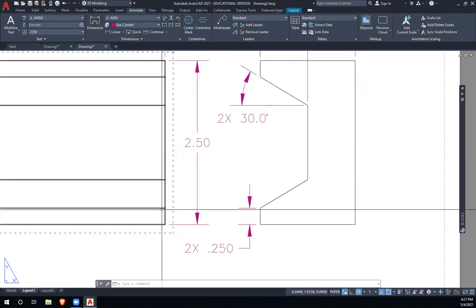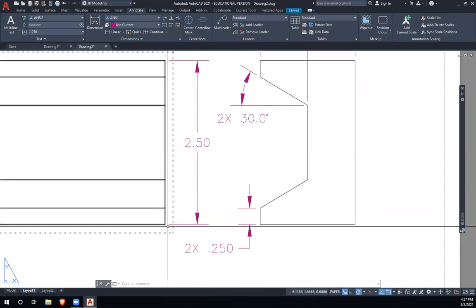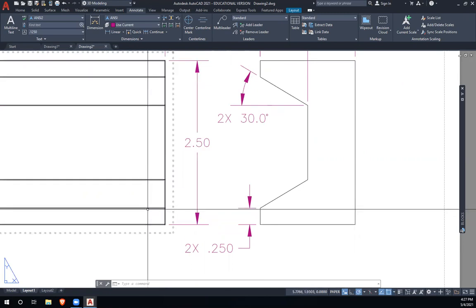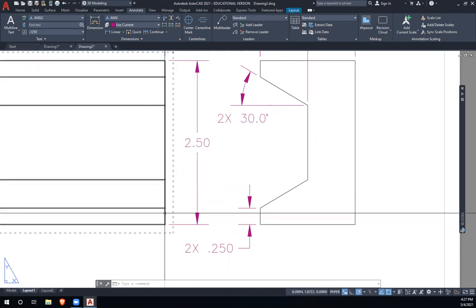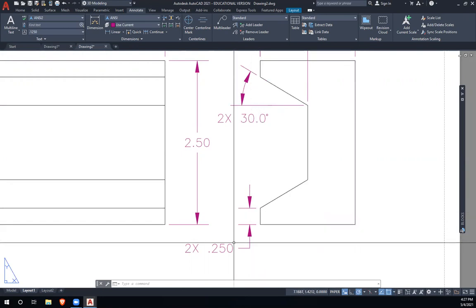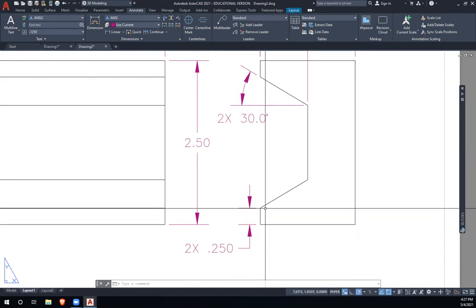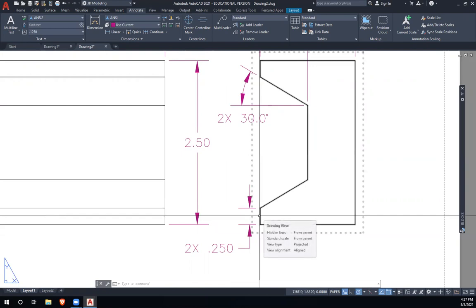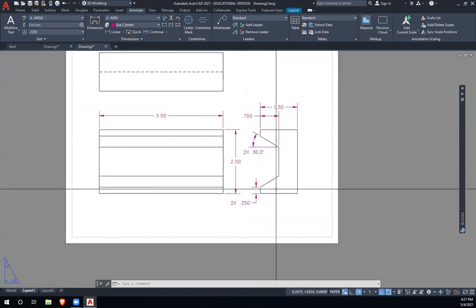I could have put it on the front view, but I don't see the shape of it in the front view. I just see a line going to another line, right? Whereas I see the shape in the right side view, so I preferred to put that 1/4 inch dimension on that view for it. Okay, so grouping dimensions, keeping them off the part, dimensioning where you see the shape of it. Okay, you shouldn't have to do a bunch of math to figure out how to make this thing, right?